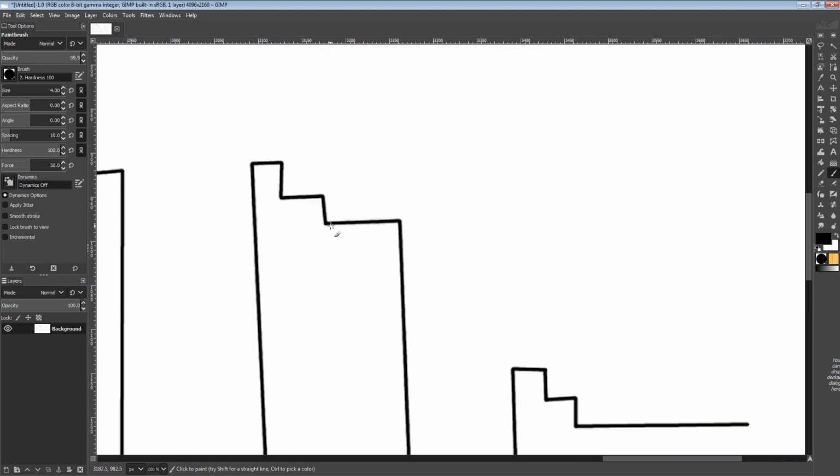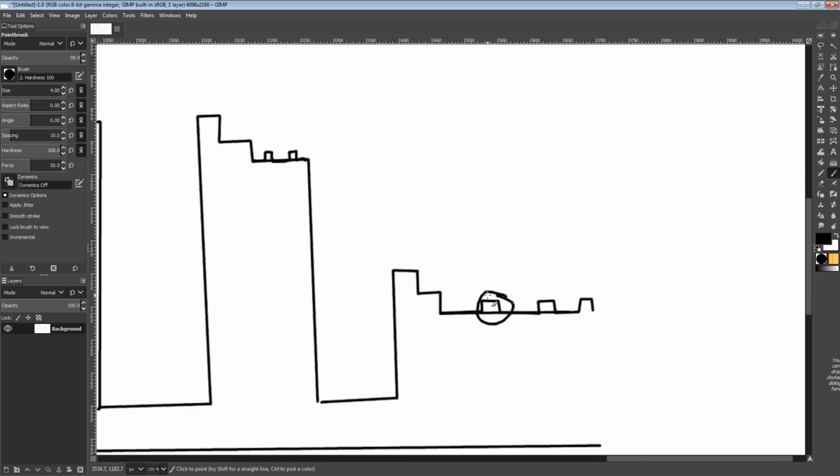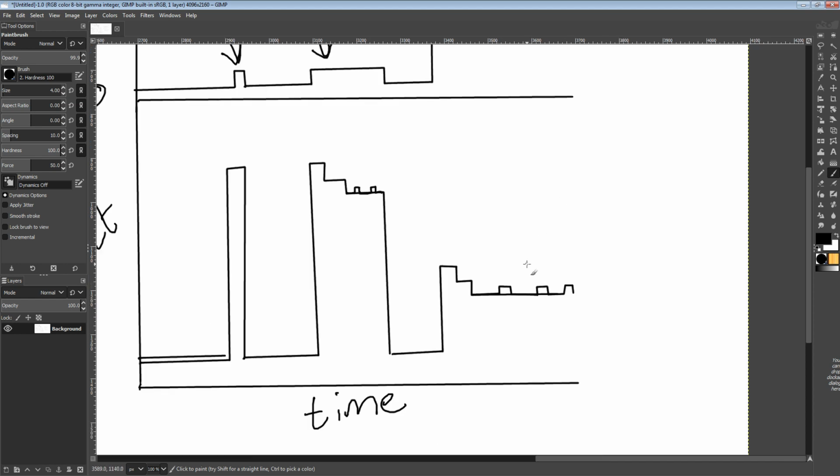And the funny thing is, I'm drawing this as a straight line, but actually you'd still have little peaks of voltage. For some reason, I think that's a behavior AMD just needs to take out of their algorithm, because it makes it really unpredictable and annoying, in my opinion. These little boost nubs don't do anything. They don't increase your performance very much. But if you're messing with BCLK overclocking or PBO or that kind of thing, they are annoying to deal with because they're a stability hazard. They aren't a performance booster because they don't happen frequently enough, and they don't boost high enough, to make a difference to your performance, right?